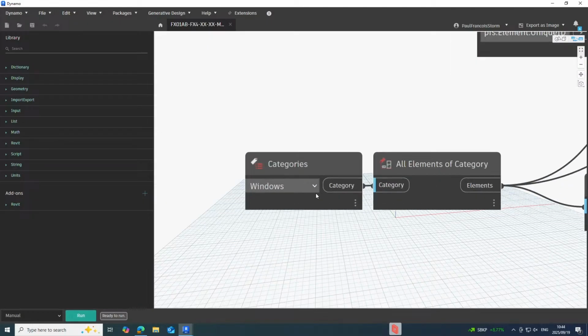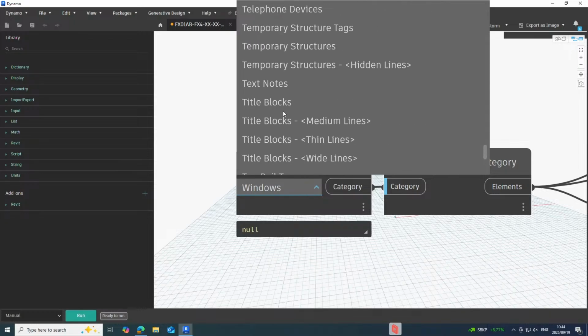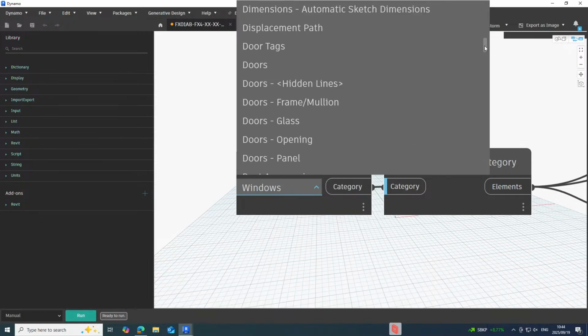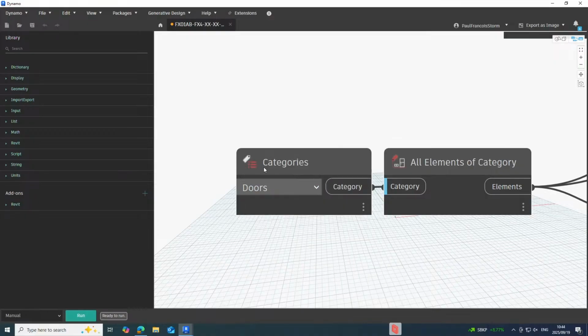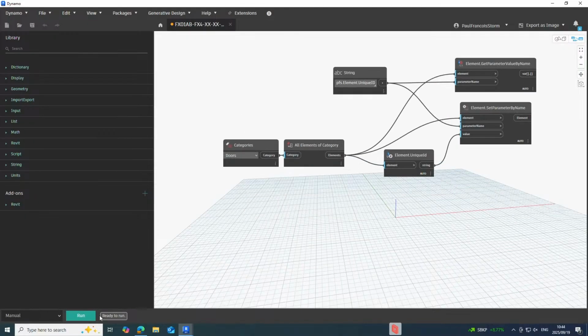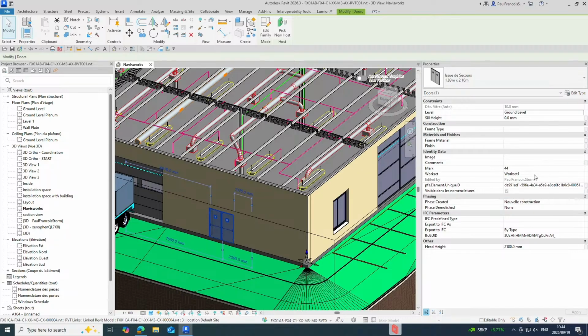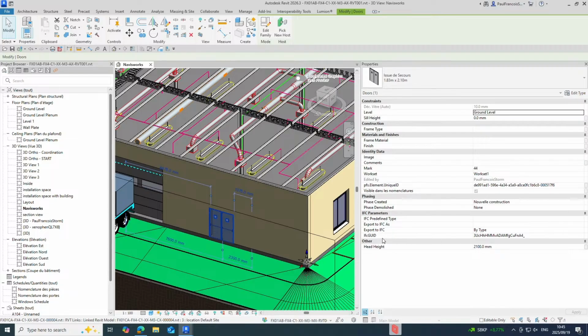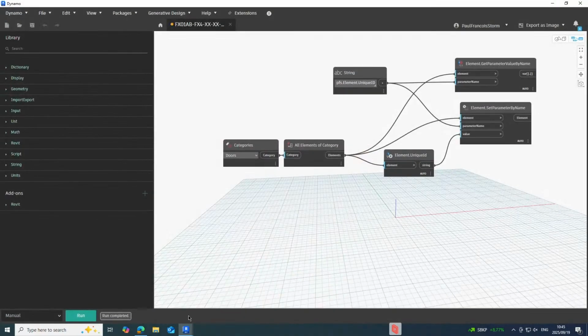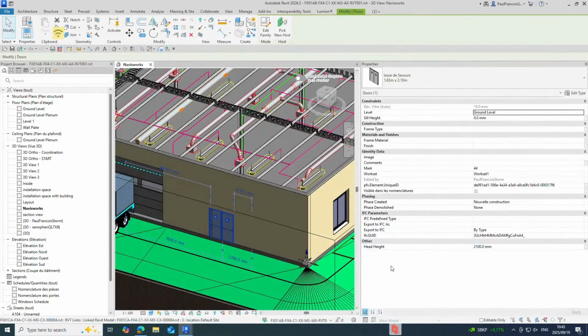So the idea would be to select all the doors, whatever doors there are. So there would be some doors, and then if we run that, it should map onto the doors the global unique identifiers. So there's the doors global unique identifier, and then one would also be able to set the IFC GUID in a similar manner. So, you know, if you had to use the same methodology over there, I just want to get the name of this IFC GUID, small and then big. Someone could do the same thing over here.